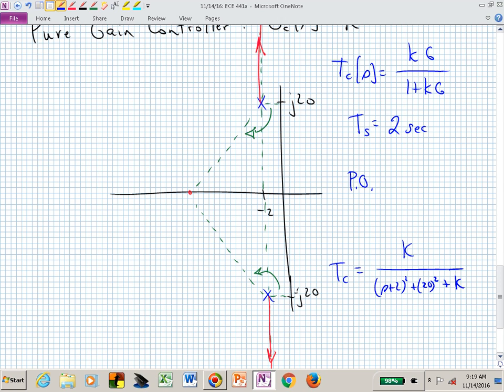That's the closed loop transfer function, and there's my denominator. And what happened to the linear term in the denominator? It's not impacted by k at all, is it? It's still this s squared plus 4s plus 4 plus 400 plus k.